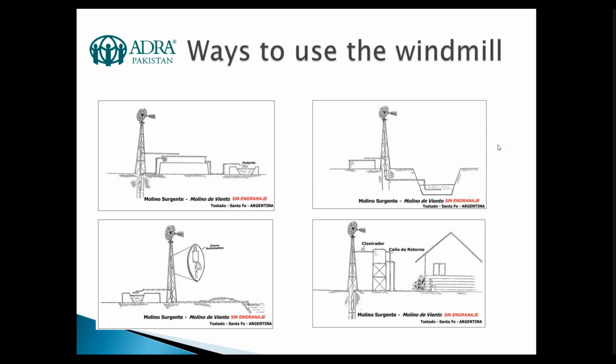Yes, when the wind goes up to 60 kilometers per hour, the tail of the windmill starts turning against the propeller. It has an automatic way to shut down, to stop working, and that protects it. If the windmill alone gets 100 or 80 or 90 kilometers per hour, the fan will be destroyed. So many revolutions, and then it will be destroyed.